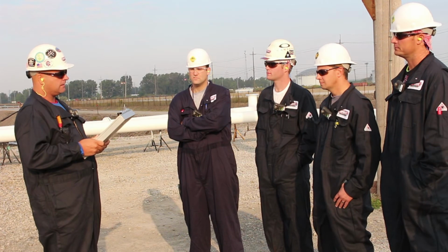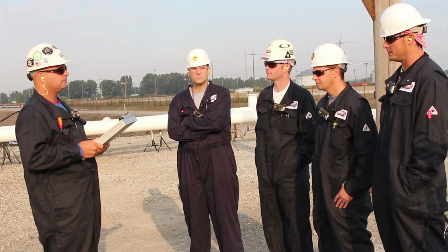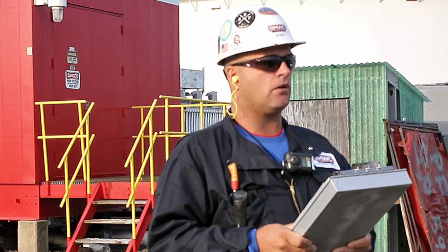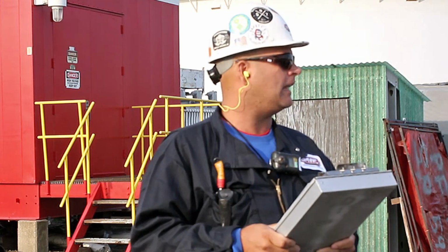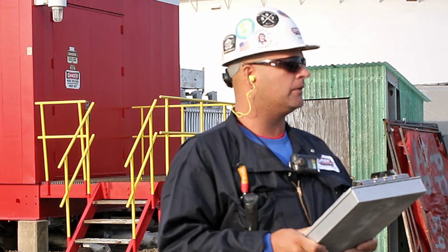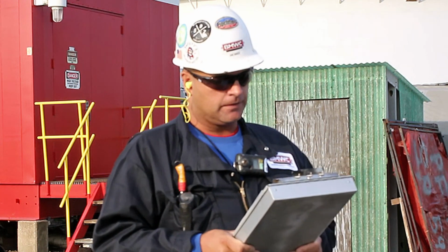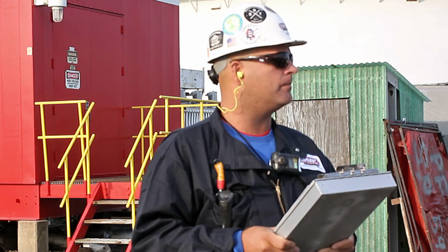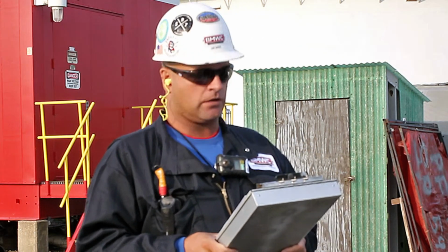The MSDSs, does everyone know where to find them? Control room. Yes, the MSDSs are in the control room, correct. Zero energy is verified. We have open lines. We verified that the other day. We will double check before we start. Everybody, please inspect your fall protection before you put it on. Check for frays and burns.